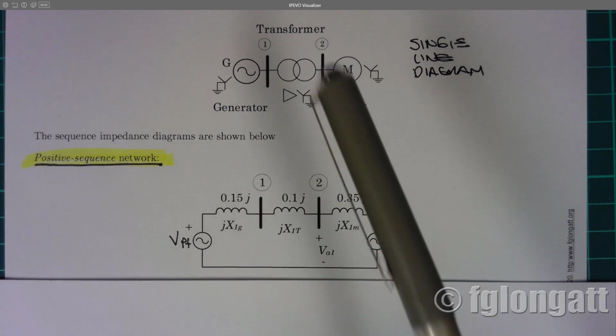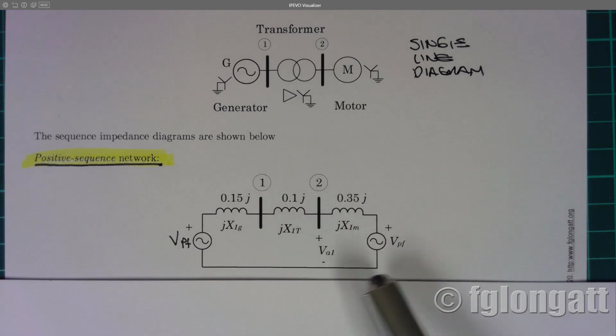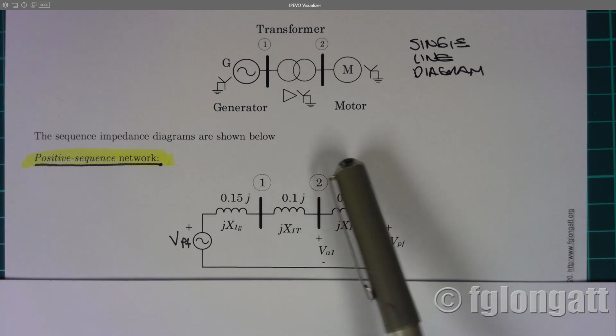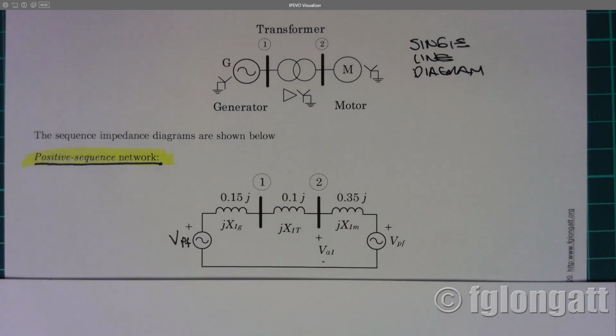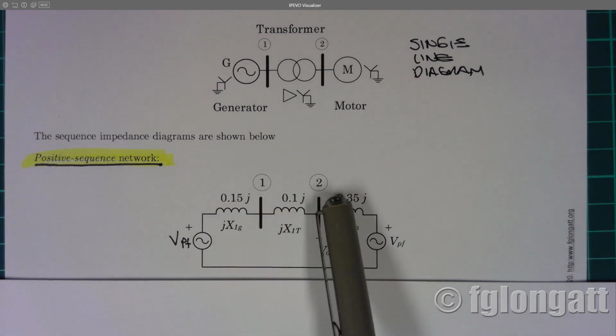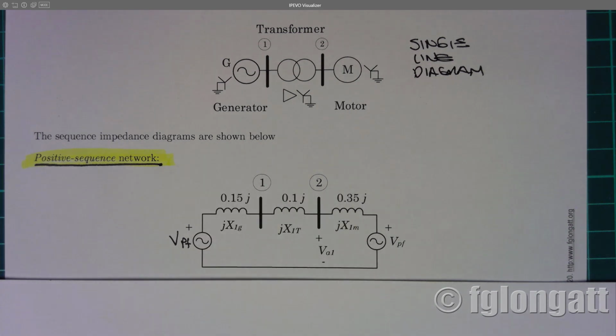And something similar is happening with the synchronous motor. The equivalent model for the synchronous motor, we are using an ideal voltage source, series connected to a positive sequence reactance. In the middle, between bus bar number 1 and 2, we have here the reactance, okay? It's extremely simple.